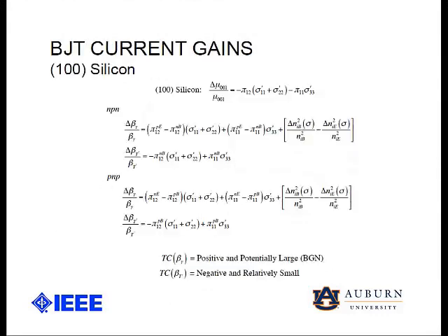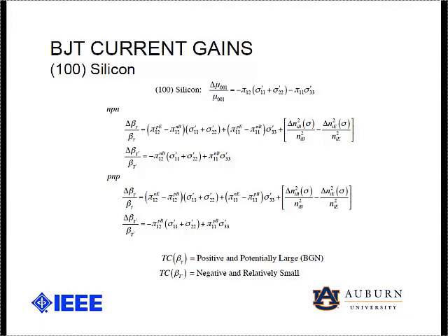So if we go into the 100 surface, we're interested in the mobility now in the vertical direction in the transistor, changes in mobility induced by in-plane stresses as well as the out-of-plane normal stress. So it's pi 11 and pi 12 that enter into these expressions for the current gains. And we have the mobility variations here, and again, Ni squared in the beta gamma, and in the beta T prime, it's just mobility. So that's a big difference here if there's any band gap narrowing.